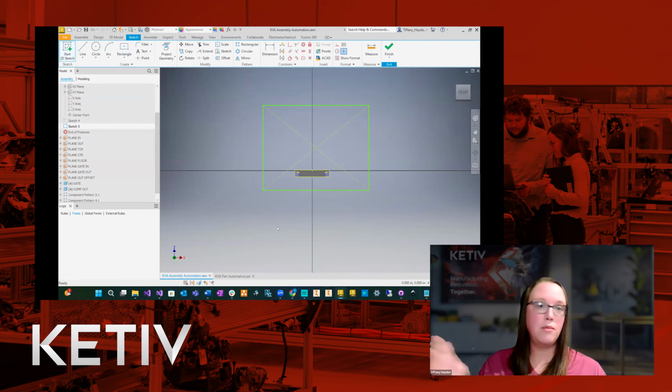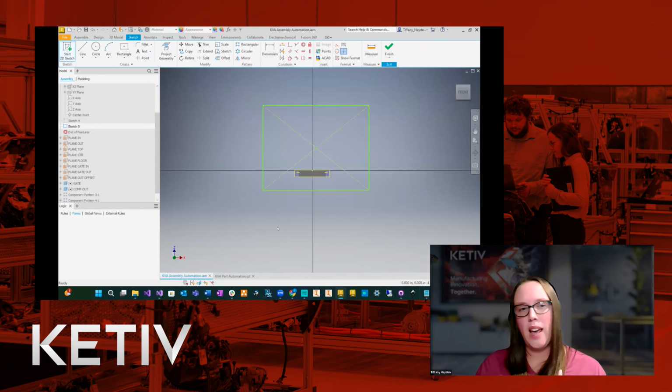A lot of times you want to draw it away because if you have certain settings, the auto projecting of geometry happens, and you may inadvertently turn things on or auto project things that you didn't mean to. So it's good practice to draw your stuff away, or at least to where it's not hitting your other material, if it's possible for what you need.